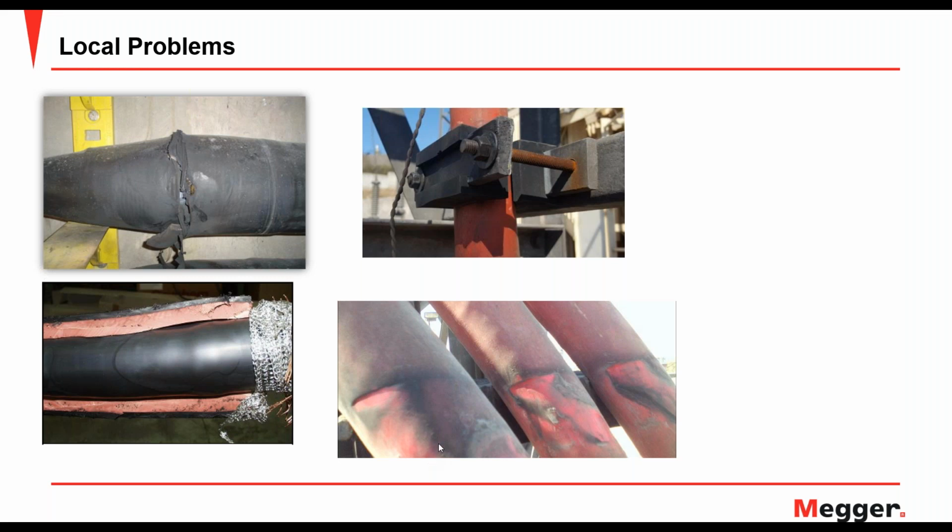And similar to the bend radius, what that's going to do is affect the electrical field distribution at that point, and again is a prime point to have some partial discharges or other defects taking place. And that's going to be in the main insulation, obviously, between any of your splices or terminations.